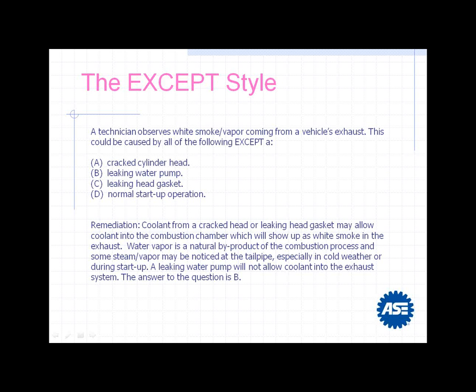So again, this question is testing our knowledge of engine failures that can result in abnormal color smoke emitting from the exhaust. We could have spun this question a couple of different ways. We could have asked about black smoke or blue smoke, looking for maybe a rich air-fuel condition, or blue smoke burning oil. So a lot of different spins we can do on the same theme, and then come up with different answers to that question. But again, it's the idea of extracting that key information and understanding how it applies to the content of the question and what we're trying to test from you. Okay.